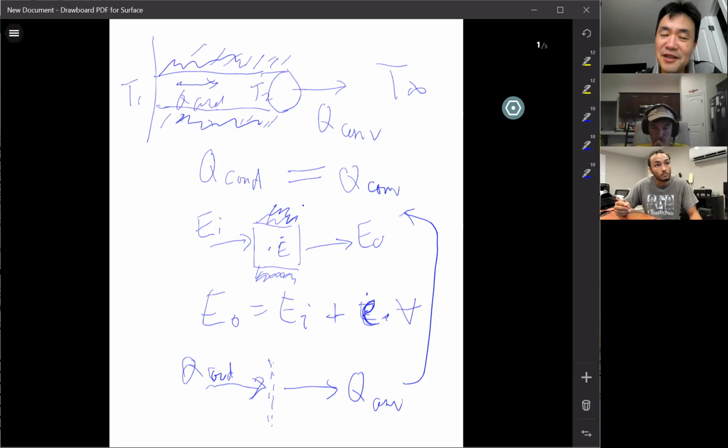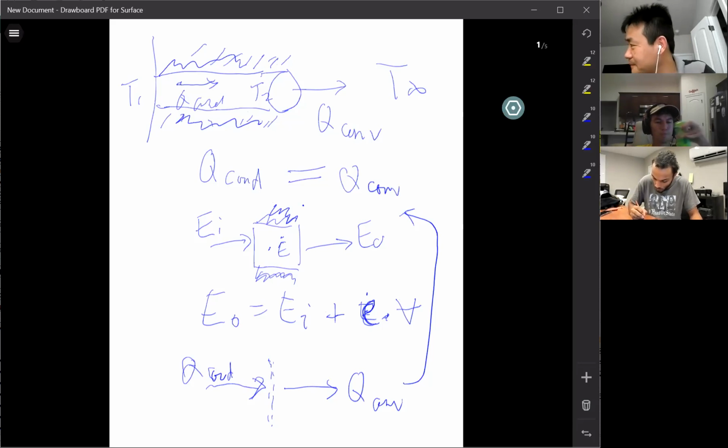So that's the fundamental principle. If you have multi-mode heat transfer, you probably want to identify the cross-section, the interface between the different modes: conduction, convection, radiation. Then you can first write down the energy balance equation. Through that surface, in and out, they have to be equal.